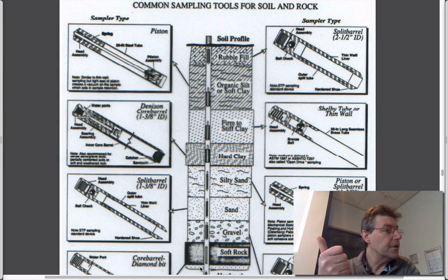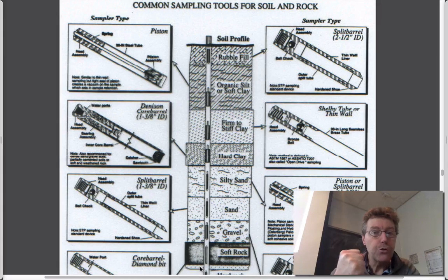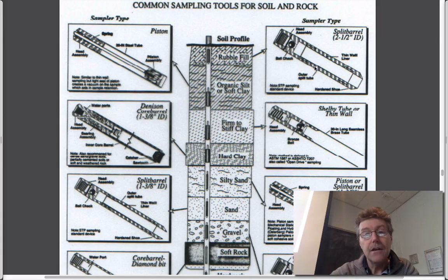Soils that are granular, you have to bang a tool into them. And because you have to bang a tool into it, because sands and gravels are quite resistive, the wall of the tool is pretty thick. And it has a cutting shoe on it, which is also quite substantial. So that when you enter it into the borehole and bang it in with this monkey hammer, you don't shatter the walls of this or buckle the walls as you push it in.